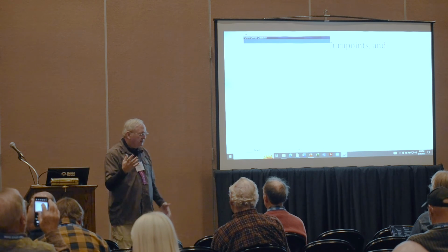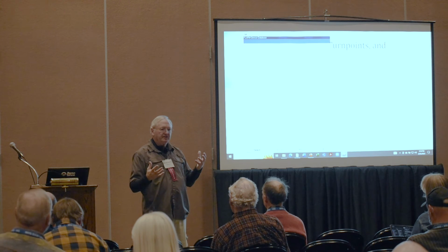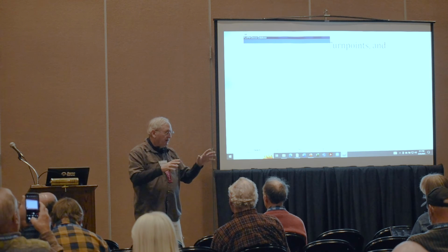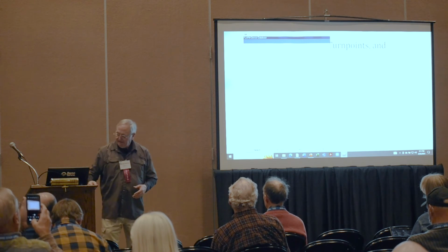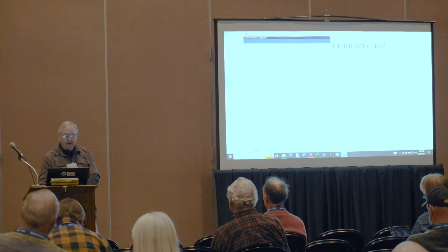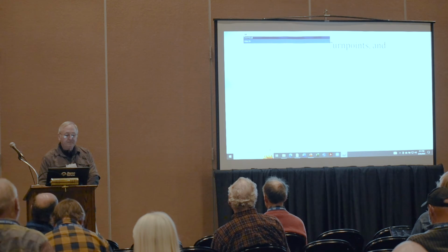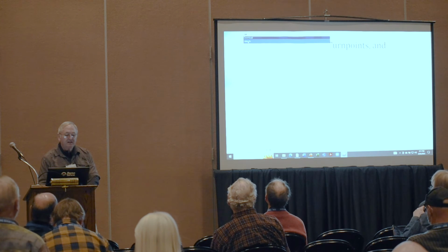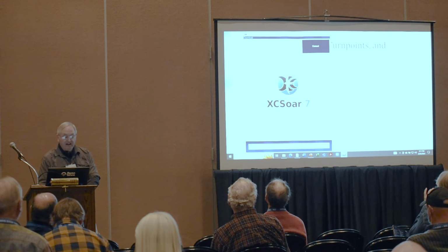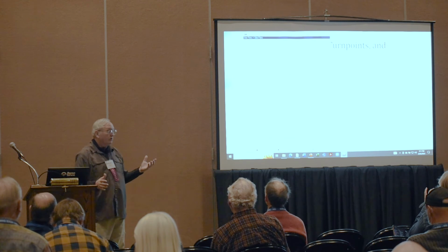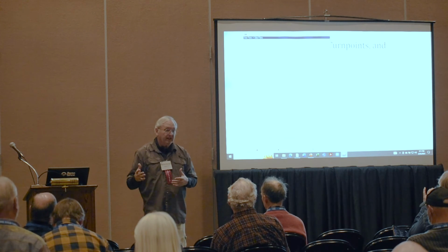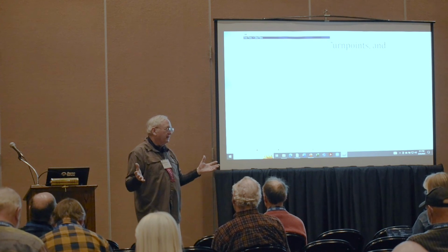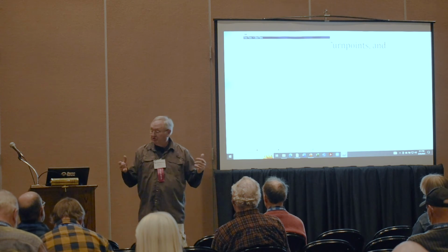The last thing is if you have a FLARM device and you're receiving FLARM data, if you have a FLARM and you have some kind of FLARM display, the advantage of it is you can identify who's around you if they have registered their airplane. And so that's called an FLN file, or a data file, depending on the format. But you can go down here to download again and take the data.fln and click on that, and I don't know if that's worldwide at that point or whether that's localized. Again, more accurate, right? The FLN file, I think, is worldwide. I don't think there's any regional information there.